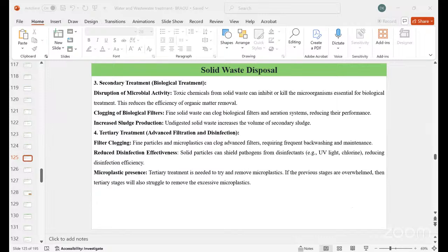That is how the liner helps, and there is a cap cover also, so that through wind or air there will be no dispersion of the solid waste, and it is more compacted in size as well. And the leachate and drainage collection is also present, where that can be drawn as and when required, and will be collected and treated further. And the wells present are also not at all affected because of these advanced modern landfill technologies.